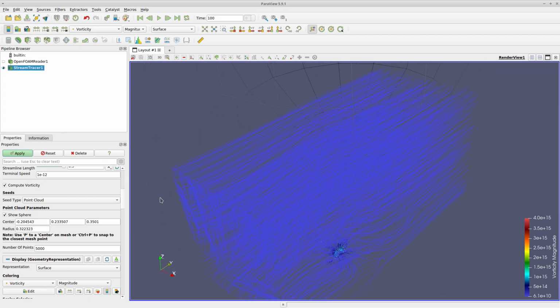Again, I think the poor results are partially due to the fact that I did not model my city very well. I probably have some sharp edges or the need for mesh refinement or any number of things that could go to having bad results. But again, the idea is if we just subdivide some faces and change their velocity, and depending on how many faces you use and depending on what kind of pressure gradients you need, that could be a way that works pretty well.